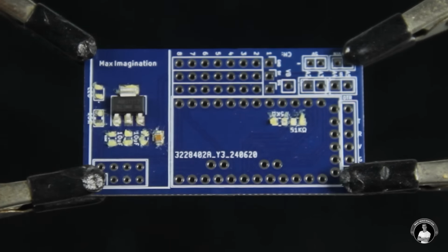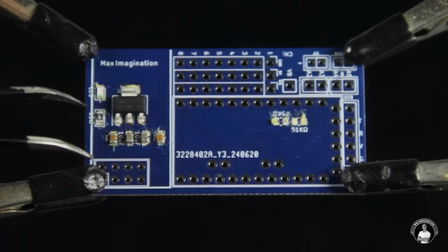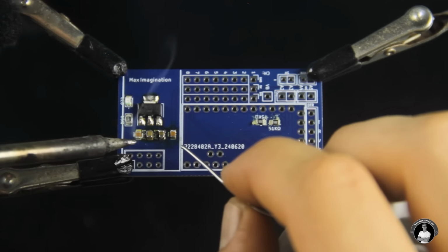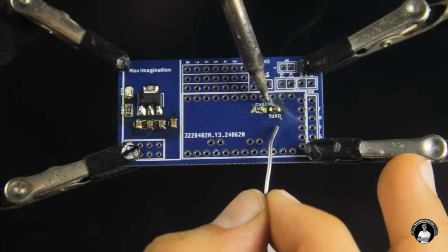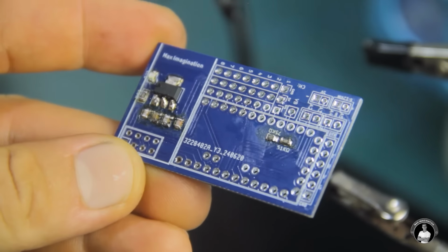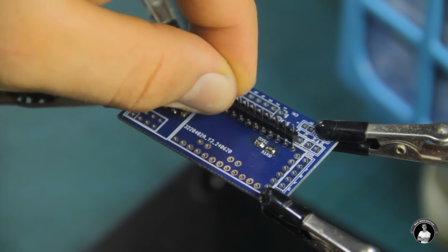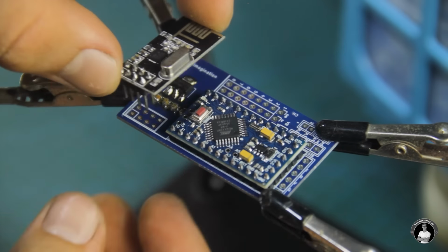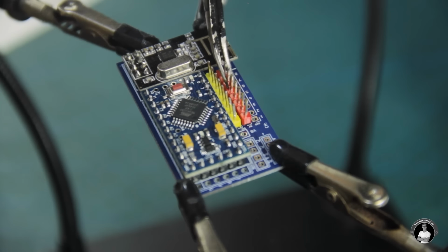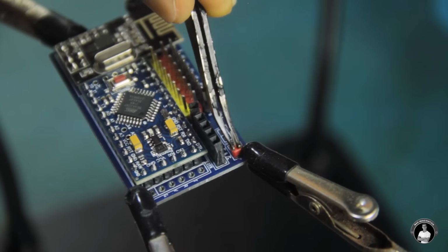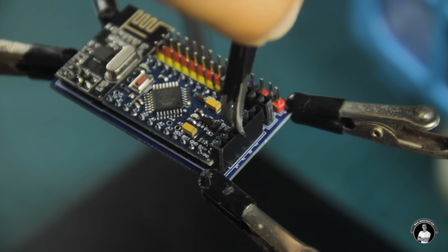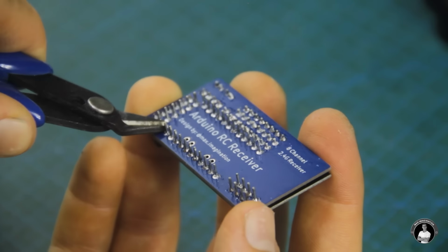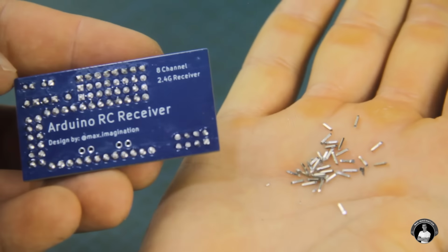So normally when soldering SMD components onto a PCB, you'd use solder paste, but as I didn't get some prepared, I'll instead use solder flux as paste and soldering tin to bond the components. With the surface mounted components in place, we can begin installing the Arduino Pro Mini, NRF24 radio transceiver, peripheral pin headers, headers for voltage monitoring, analog inputs, power inputs, and for programming. And after a bit of soldering and pin clipping, we have a receiver.